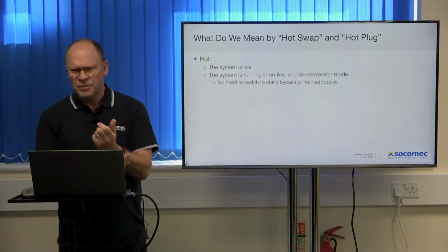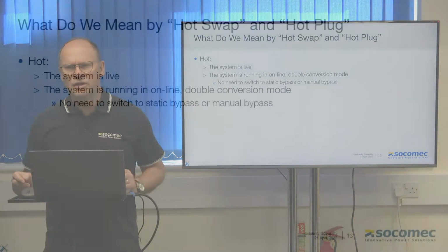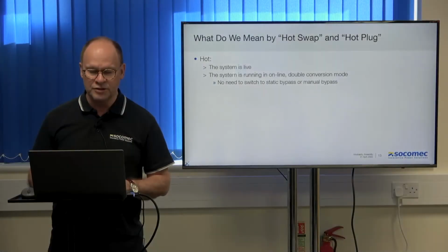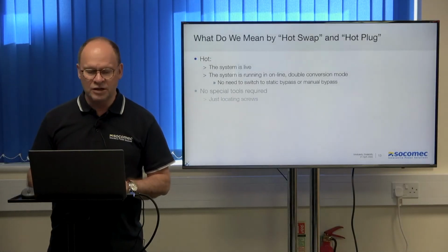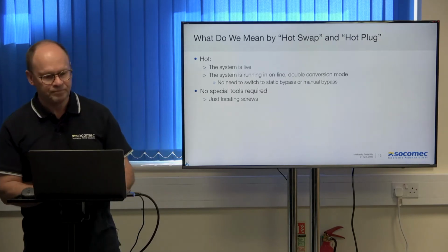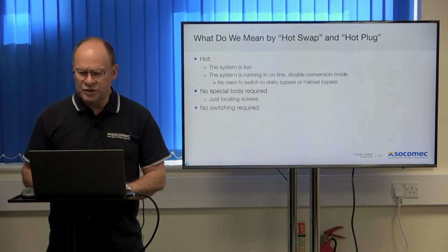Hot swap, again, people saw it. Most modular UPS manufacturers will class their system as hot swap, hot plug, but we like to put some definitions on that. Firstly, the system has to be live and online. That's what we mean by hot plug. You just plug it in. You don't need to switch to bypass, either internal bypass or maintenance bypass. There shouldn't need to be any special tools required. In our case, you just need a screwdriver. And we wouldn't expect any switching to be done either.